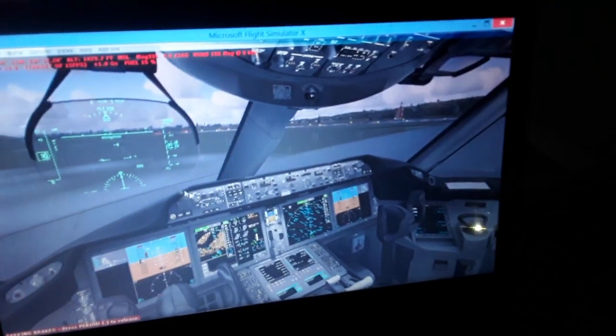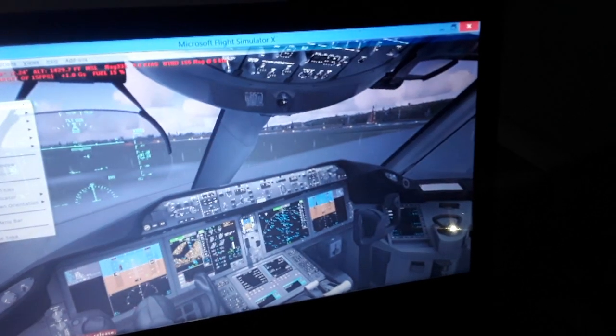We're also going to have the LSZH localizer frequency tuned either automatically using the flight management computer or manually using the radio management panel. We're going to have the flaps set to 25 or 30 degrees, an airspeed of 160, 170 knots for approach and landing, and a pitch attitude of 9 degrees or less until touchdown on runway 14 in LSZH in Switzerland. We're also going to have the landing gear down, and this is all for the flight plan.